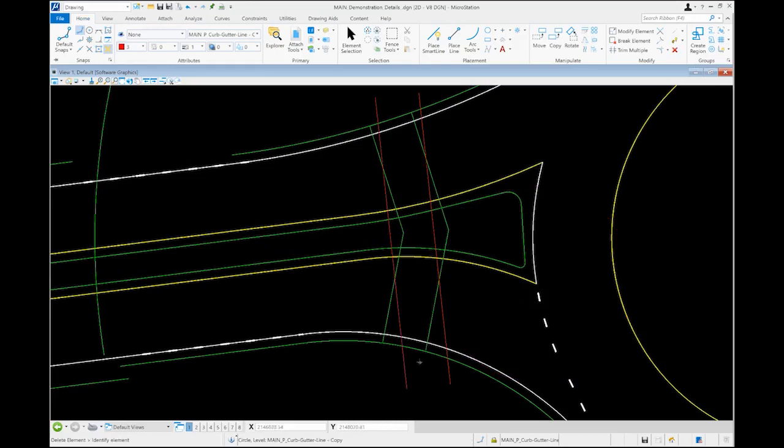The pedestrian crossing ends up in about the same place from a pedestrian navigation standpoint. It's a straight crossing for somebody that might be visually impaired. But the key here is if you go down this type of strategy, the ramps at either end of the crossing would not be able to be perpendicular to the curb line. They would need to be in line with the crosswalk itself so that the pedestrian, as they're reaching the crossing, is aligned with the crossing location.